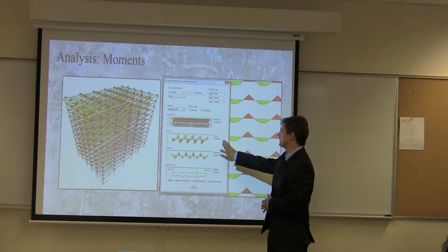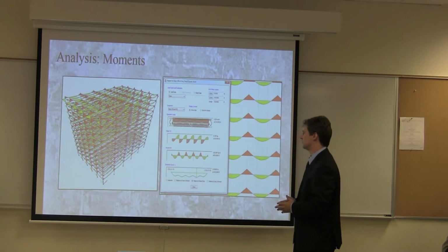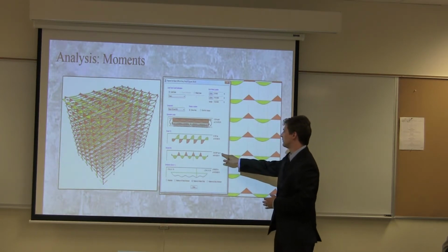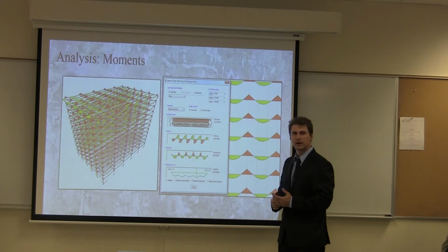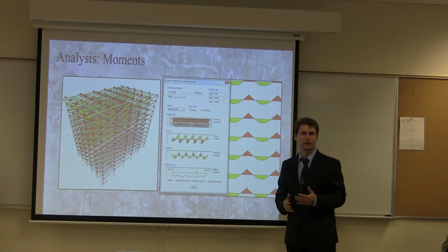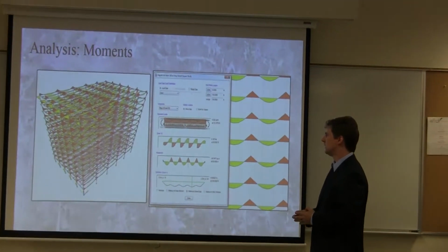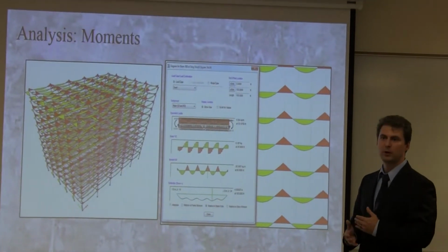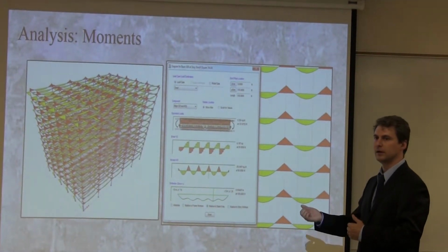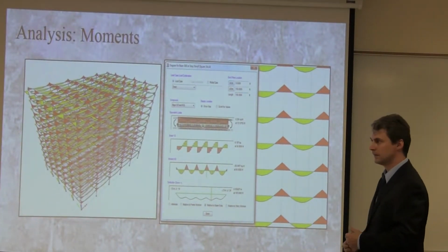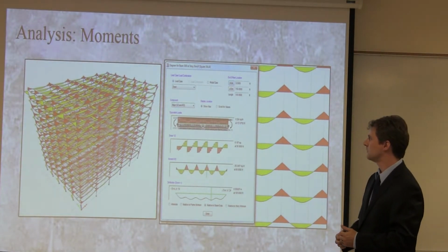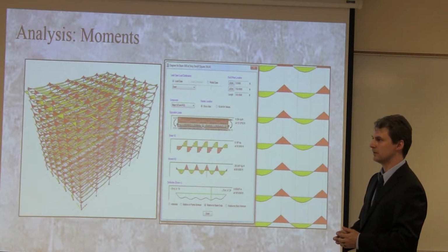If you look at the dialog box here, we've got the shear and moment diagrams drawn up, and it gives you the actual values. I'm sorry that's a little blurry to see. That's what we used when we did our hand calculations, so that we could ensure that what we designed lined up with what our paper calculations said we should have had. So this is the dead load or live load case. This is both. This is the analysis.